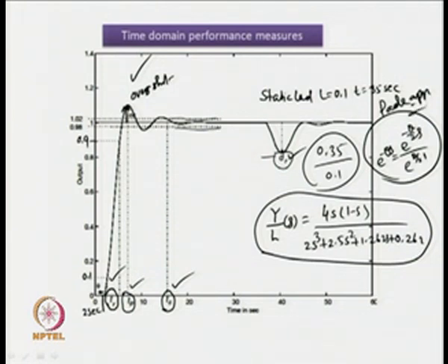Now, using that approximation, the closed loop transfer function denominator polynomial becomes this. As it appears that all the roots of this polynomial are located in the left half of the S plane, we obviously expect a stable disturbance response, or we say successful disturbance rejection by the closed loop system.